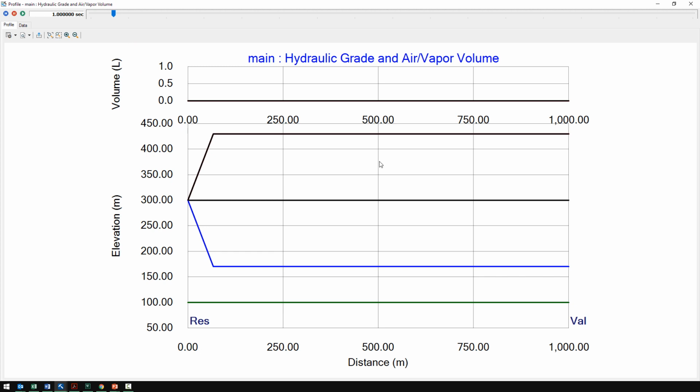So as you're moving along in time, more and more molecules are packing up against the next molecule, almost like a car collision on a highway. More and more cars will pack up behind it. So eventually that pressure wave reaches the end, and this is an open reservoir, so if I advance to the next time step, it reflects off of that endpoint, and you can see that it is then traveling back towards the valve.